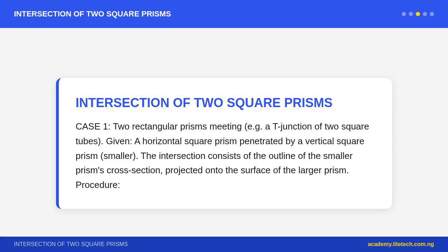Step 3. Project these intersection points from the end view back to the front view, at the height of their corresponding generator lines. Step 4. Draw a smooth curve through the projected points. This is the curve of intersection. Note: more generator lines equals more points equals a smoother, more accurate curve. WAEC typically requires 8 to 12 points for a cylinder intersection.